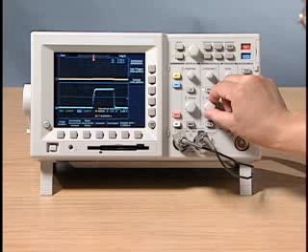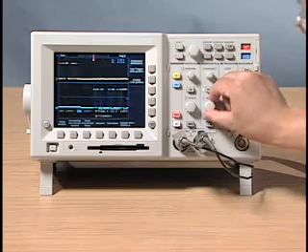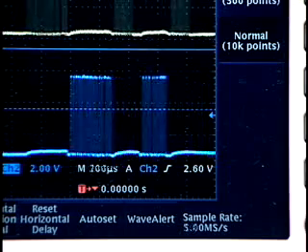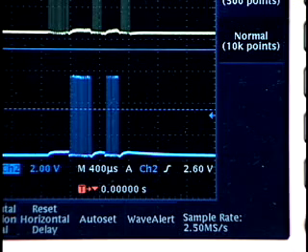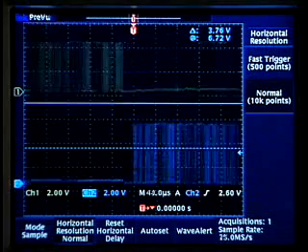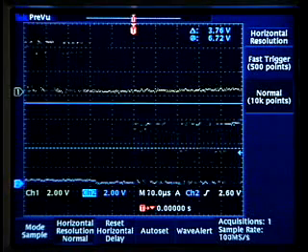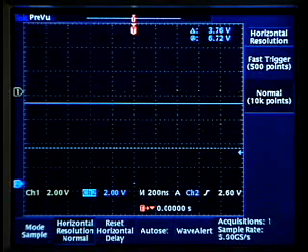One currently popular oscilloscope promises a sampling speed of several gigasamples per second and 10 kilopoints of memory. Unfortunately, this scope must reduce its sampling speed to a few megasamples per second when the time base is set to 400 microseconds per division and slower. This can be a major problem when operating at sweep speeds required to display a full cycle of typical RF baseband signals or long serial data streams having fast edges.